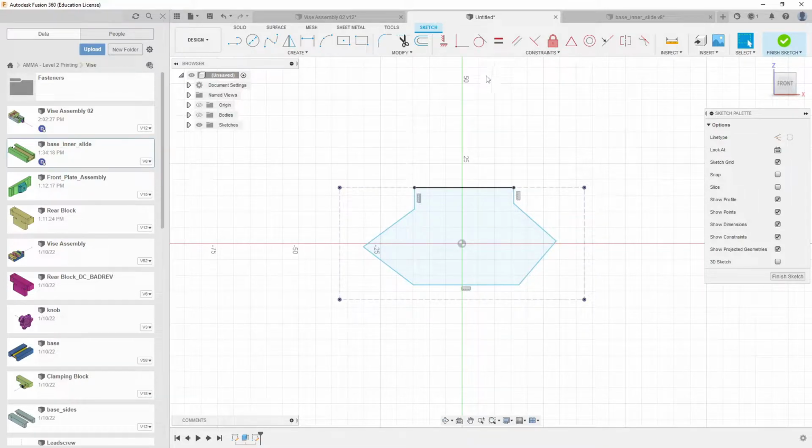So here's a trick that I do fairly frequently. You don't have to. There's other ways to do this. There's a million ways to do everything we're going to talk about. So I go over here and I change the line type to construction, and I pick this point here to that point there. What's the benefit of that? Well, now I can come over here and I can say that that is vertical, or horizontal, and that's going to straighten these things out.